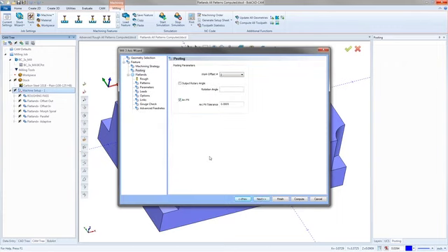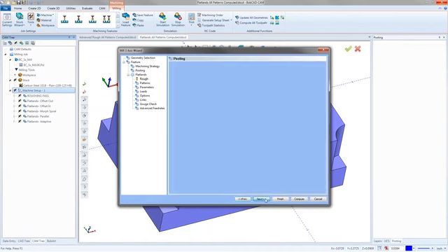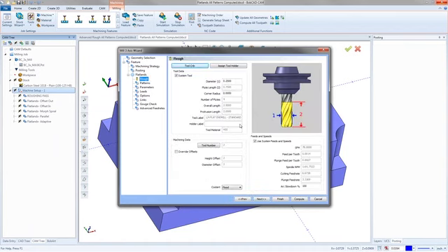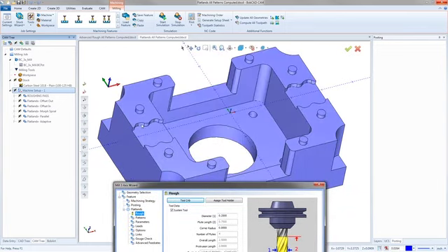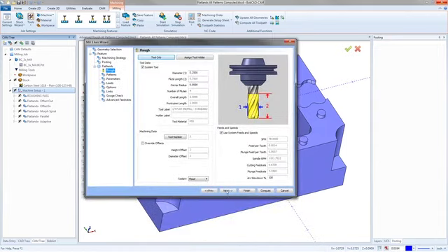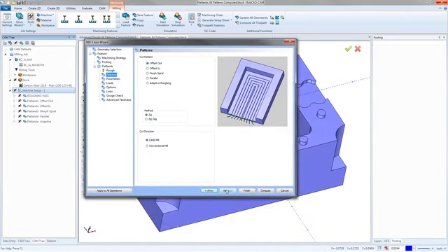Posting, again, always turn on arc fit unless your machine can't handle 3D arc moves, because this will output 3D arc moves. Right here, we then have our roughing tool. So I'm going to use a 1/4 inch on this one, primarily because I took some measurements, and this radius here, the smaller of these 2 radiuses, is a 1/8 inch radius. So I have to use a 1/4 inch tool. Not a big deal. It's just a lot more than I'd want to do.